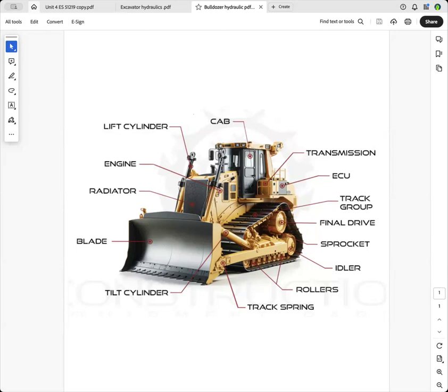And by the time we finish this, I'd like to explain that, but you have a think about it during this talk. And just think of why a hydraulic cylinder with the piston there would have a strong and a weak direction. As you can see, the strong direction is going down here, pushing the blade into the ground.